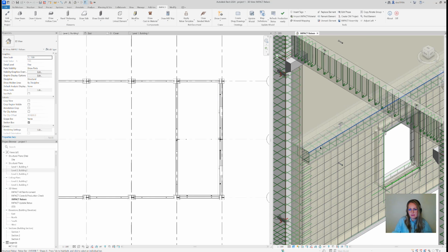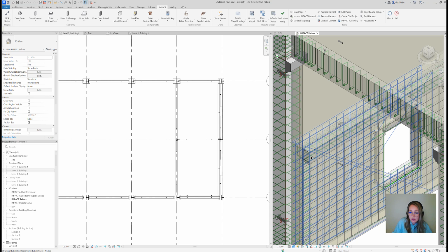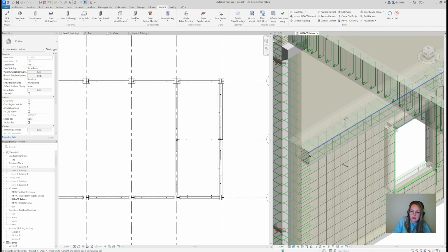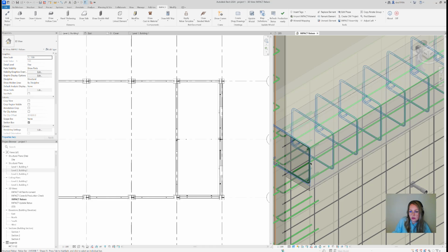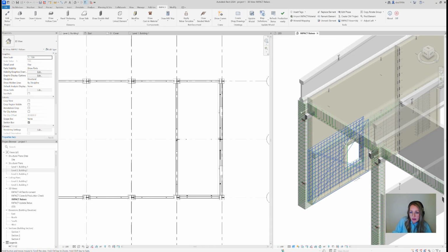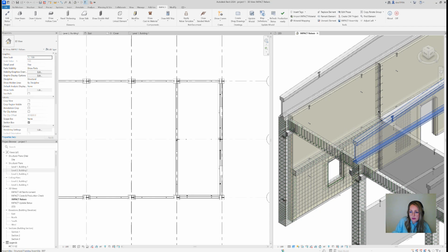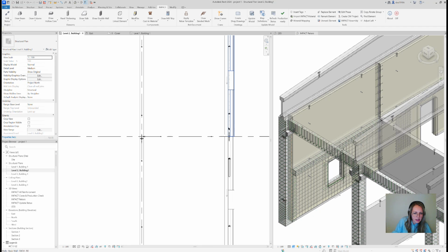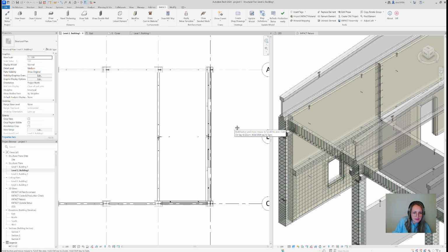Yes, so with the help of the templates, once you draw such rebars on the panel thickening, you can go and reuse it. It just needs to be the same family, not the same type, but the same family. You can have several types within the family, and we're gonna just adjust it according to the constraints. So rebar templates, very powerful tool. With just several clicks, you can see we can go and just add the rebars, right? So I can see here we can go now and add the slabs, and the time is going fast.